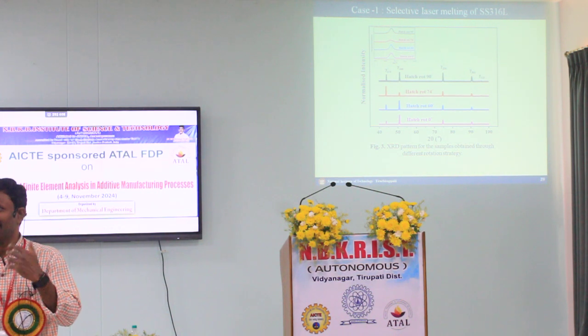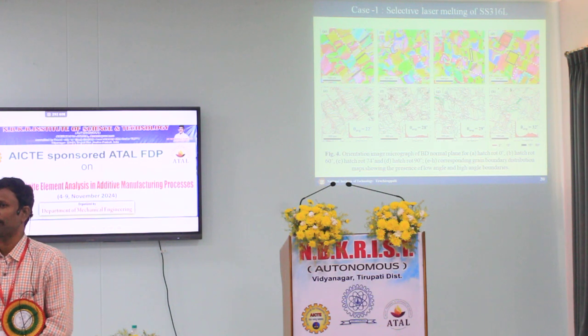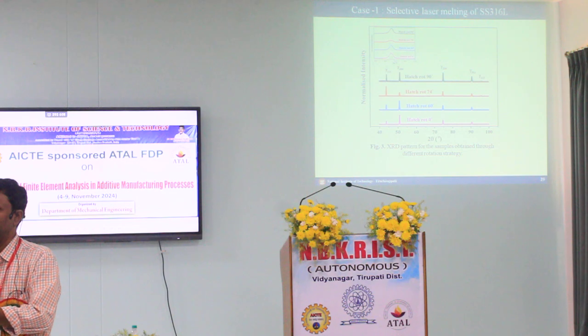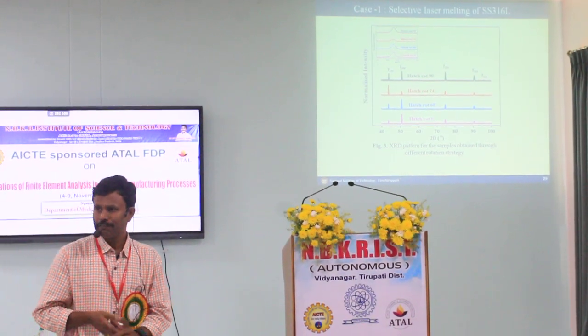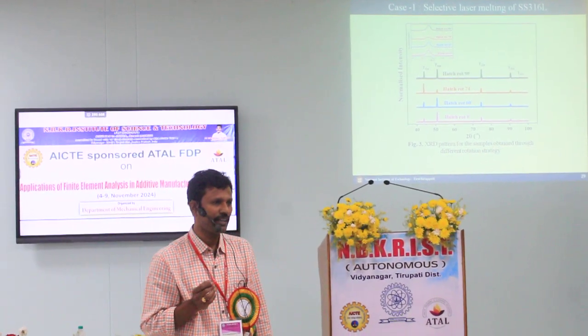Some people will say, sir, I want to see what all phases are there. You come to spectroscopy. Spectroscopy can give you only individual elements. It cannot give you phases. So vice versa. You should know what kind of information, what your requirement is. Based on that, you have to pick your characterization.